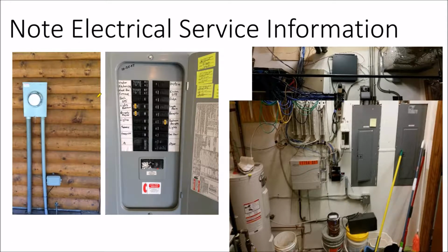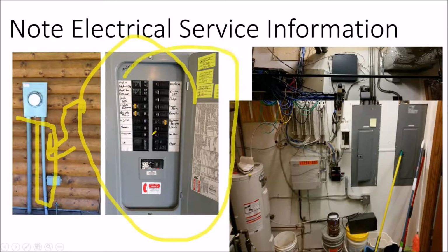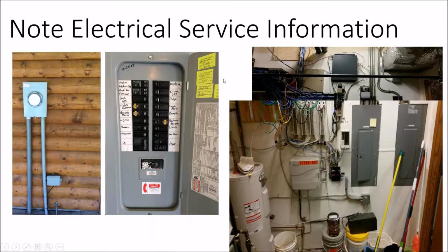and the thing is, your client has a camera on their cell phone now. So most will be happy to say, you know, if they send you this picture and then you send them instruction to go read the conduit label off of that, all of a sudden you have the conduit size for your supply side tap. You know, they can take a picture of the service panel without opening the panel up and being subject to danger.